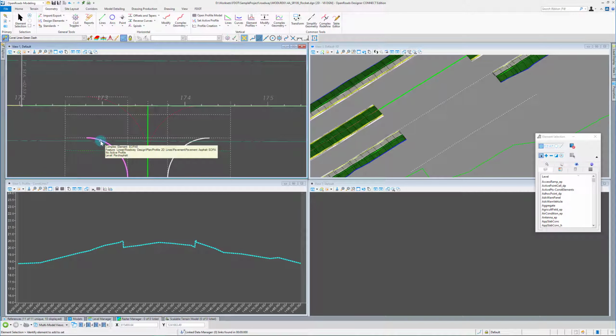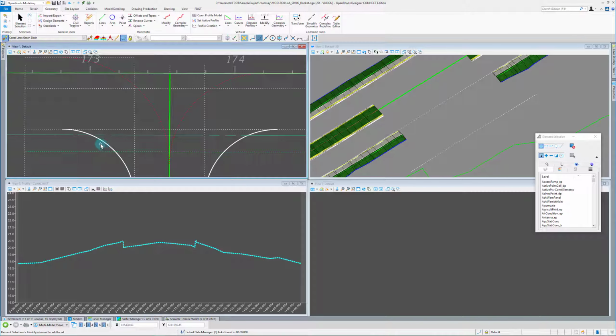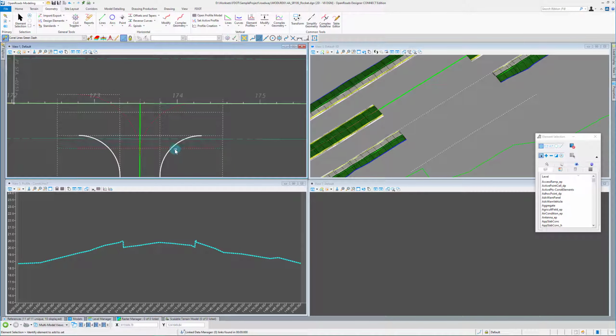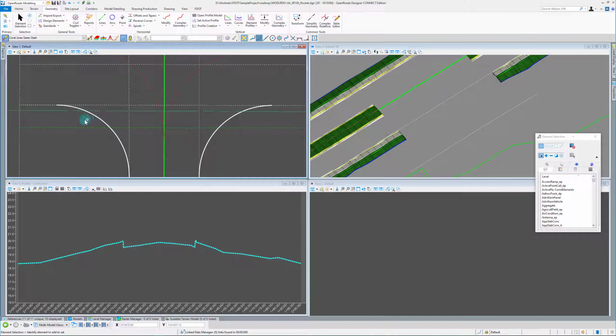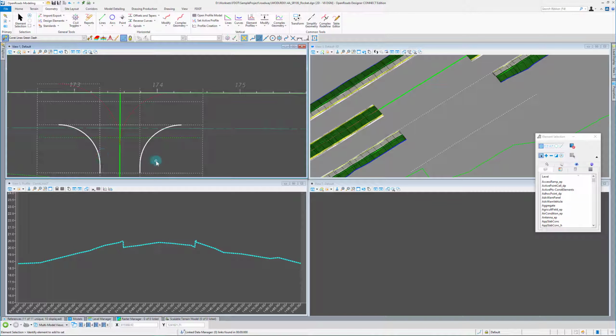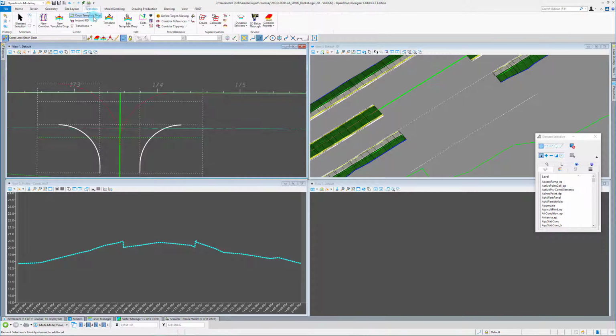We have a specific distance that we need to have for a full height curb between that curb ramp and the adjacent curb ramp. So then we'll have another curb ramp that cuts across here. And this particular driveway does not have sidewalk that continues down this side street, so we'll have a CRD, which is an FDOT standard curb that will direct traffic and go across the side street here.